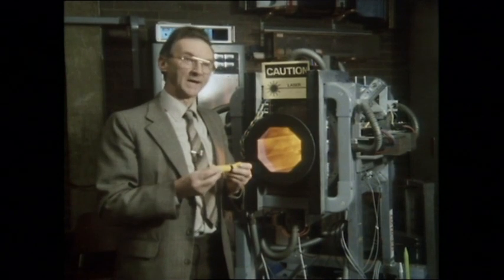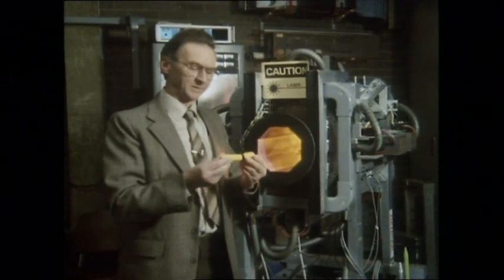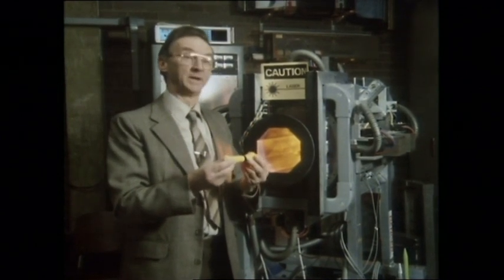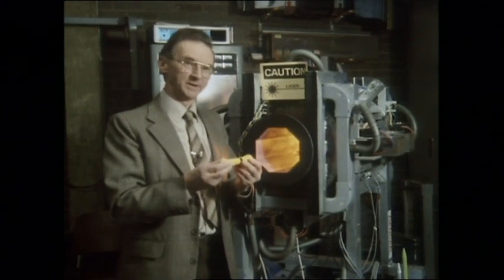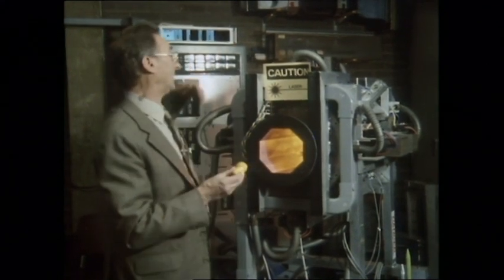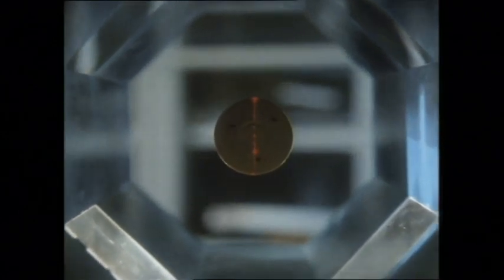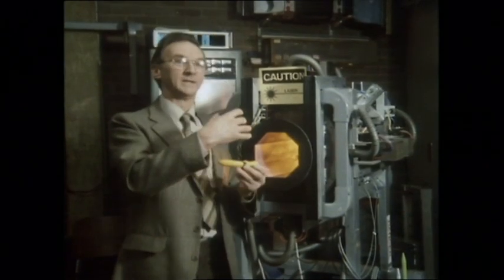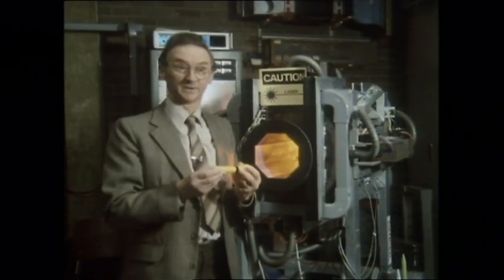We suspend the model magnetically. This model has a powerful magnet embedded inside it, and that is suspended within a magnetic field provided by the electromagnets in our tunnel here. In fact, there are 8 electromagnets surrounding the test chamber. The strength of the electric current driving them is controlled by a mini-computer. As you may know, if you suspend a magnet underneath another magnet, it will either fly up or drop out, and it's basically unstable in that sense.